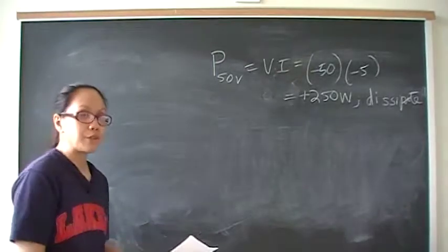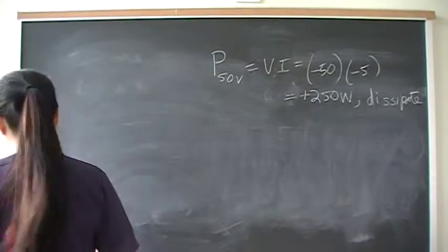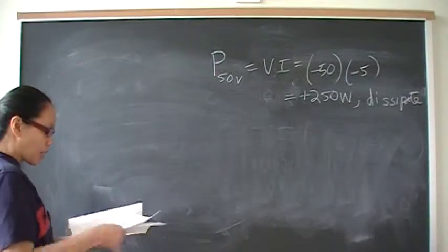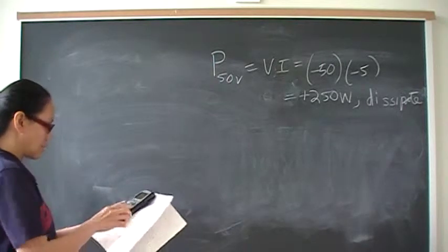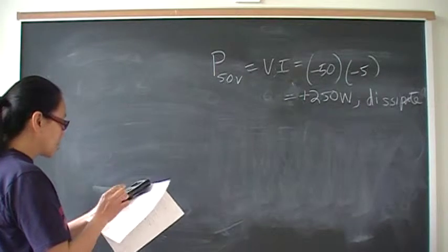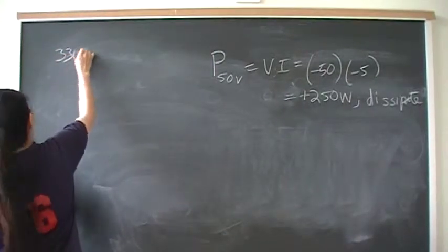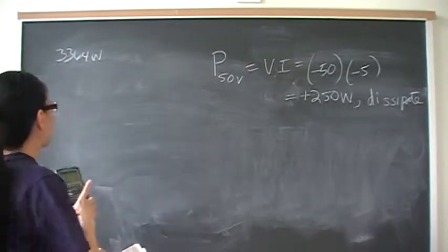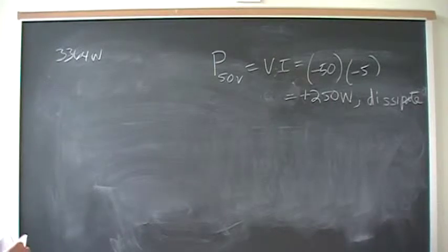Now before we do that, we're clever engineers, so we're going to add together the total power delivered as a check figure, because power delivered had better equal power generated, right? So let's add the two dependent sources that generate power and come up with a check figure. So we got 3,024, right? If you're in an exam, you should do this. You know which circuit elements deliver power, so that's going to be the two dependent sources. 3024 plus 340. They generate a total of 3,364 watts. So whatever you come up with as far as how much power is dissipated by the resistors and the independent voltage source had better equal 3364. If you have a problem similar to this, make sure to calculate what the power delivered to the circuit is, so that you can have it as a check figure.